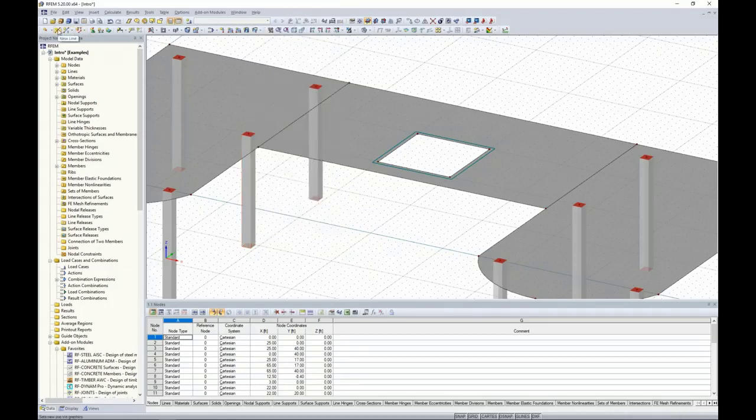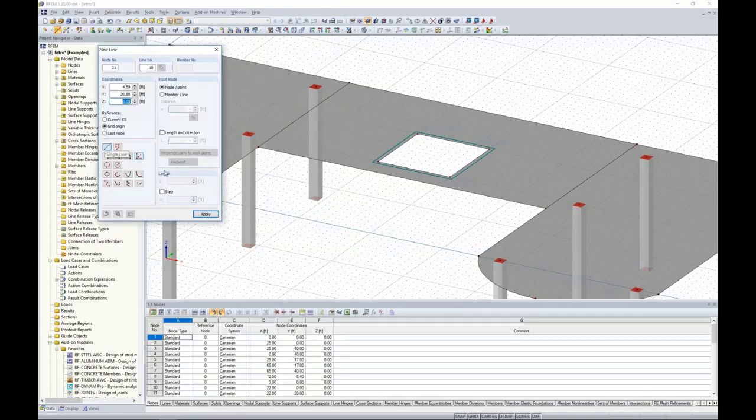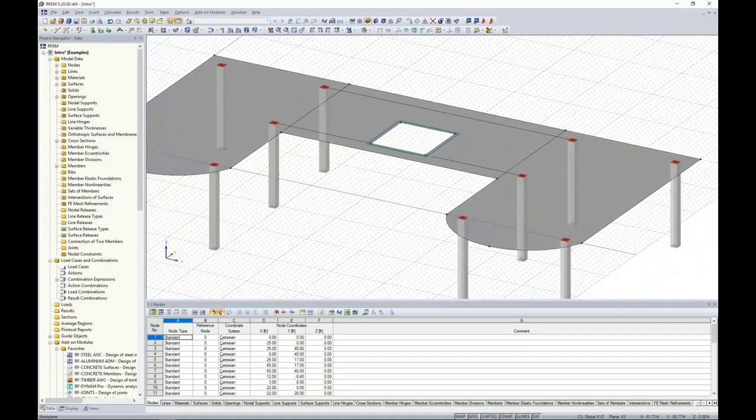So I can go back to drawing a new line, similar to what we saw before. This will just be a straight line, and I choose from the left column, and I snap to my right column. I right-click once, and I do the same exact procedure for my second set of columns here, and then I can right-click twice to exit that dialog box.